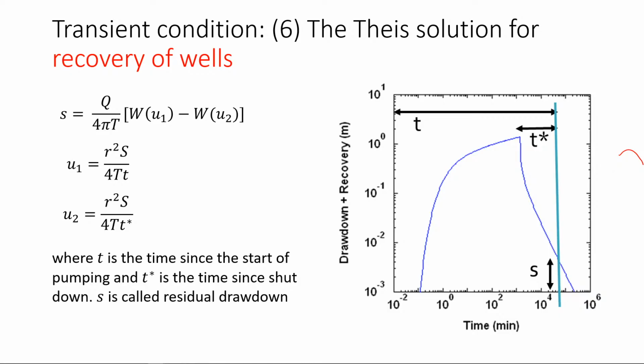You can also do recovery. So that's the drawdown: I start pumping, and then drawdown will increase, increase, increase. Then I stop pumping here, and once I stop pumping, what will happen? My water level will start to go up again. My water table will start to go up again. And that's important also when you do a pumping test.